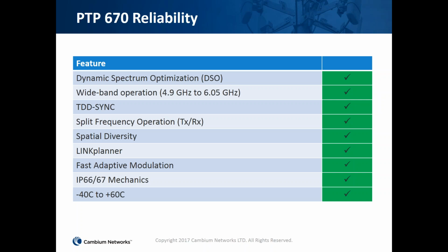What this split frequency operation helps you do is use 5.1 to transmit from A to B and use 5.8 to transmit from B to A, and then reverse the receive cycle part of it, so that you can use different frequencies to try to gain maximum channel throughput.